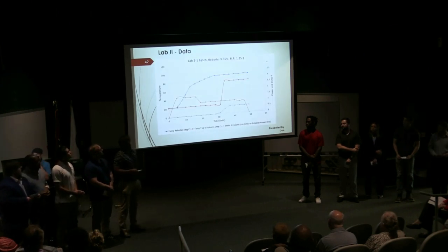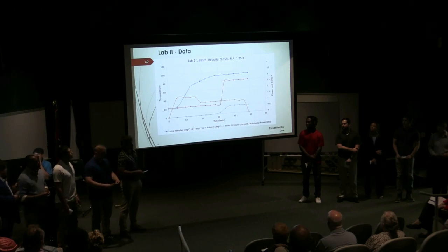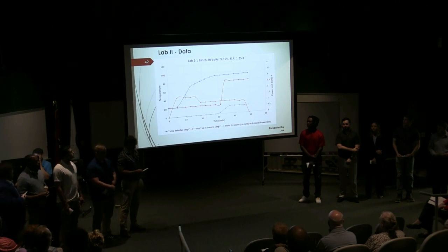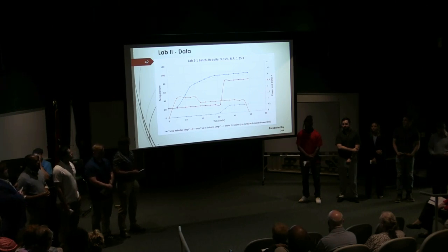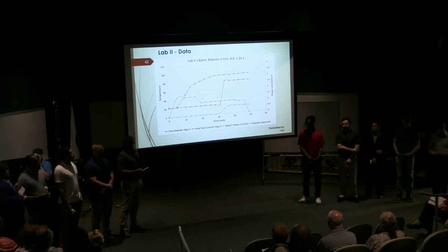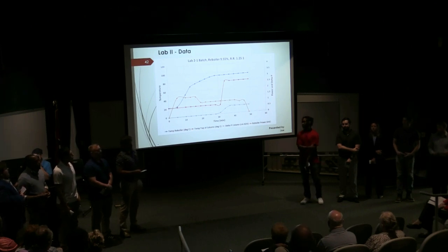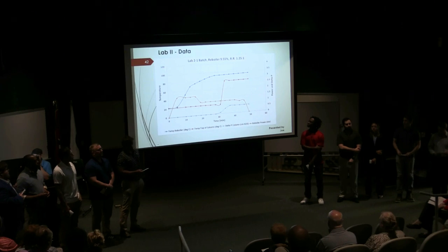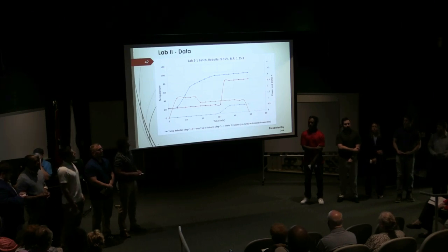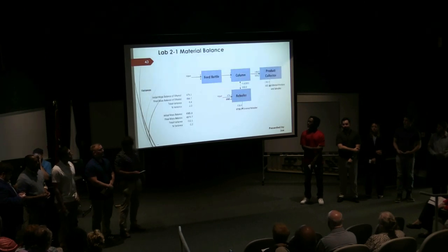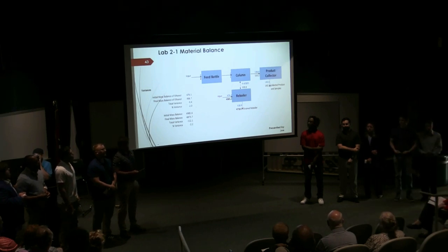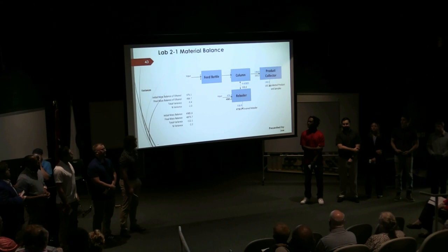In Lab 2-1, we increased the reflux ratio to 1.25 to 1. The reboiler curve behaved like the other experiments. We had more stability at the top of the column in this experiment. We made one power adjustment, and that seemed to make everything stable. Our differential pressure curve indicates a steady vapor flow throughout the experiment. Overall, this was the first stable run. In this lab, we had excellent closure on both material balances and are confident in the measurements we made.